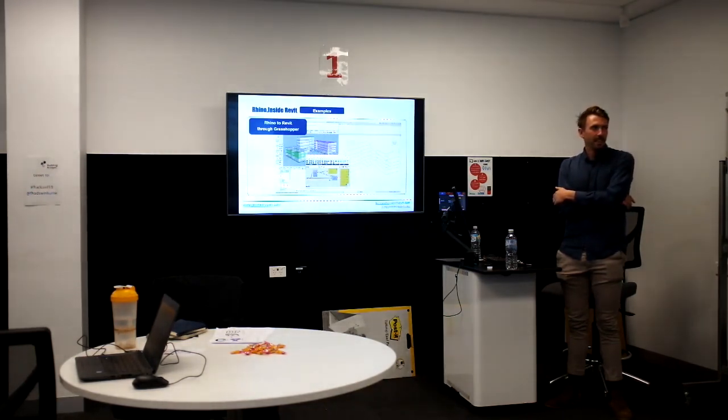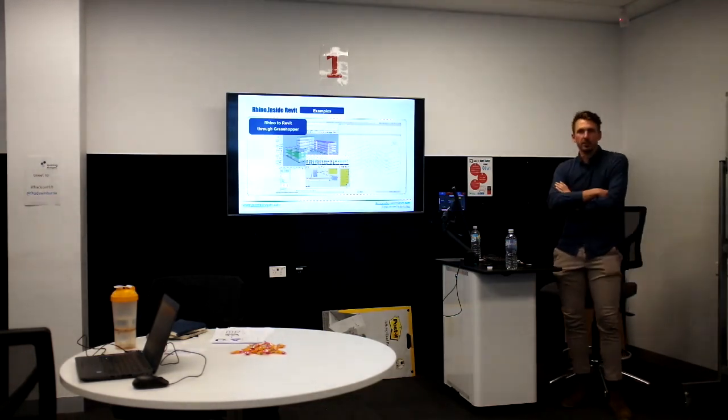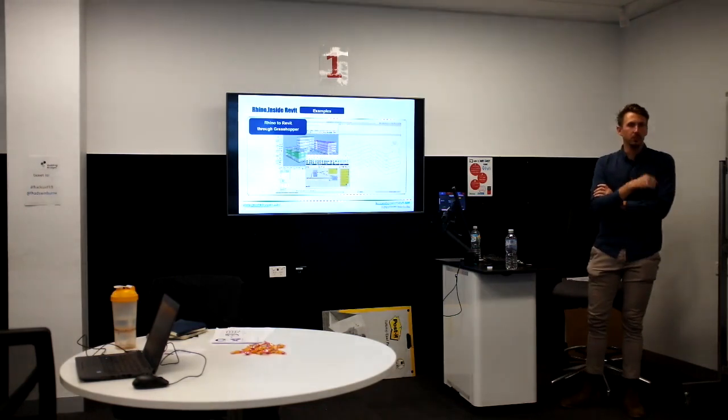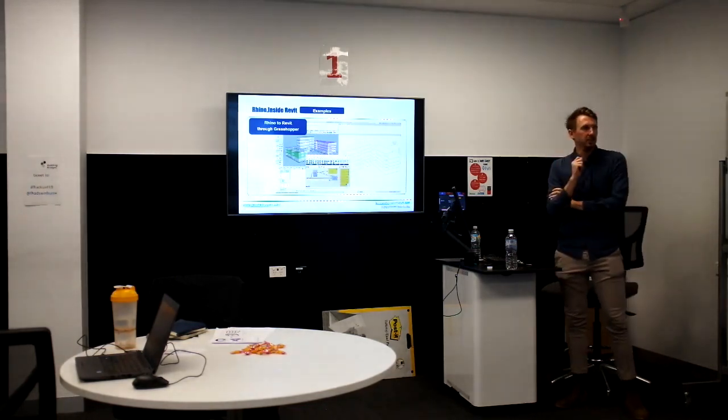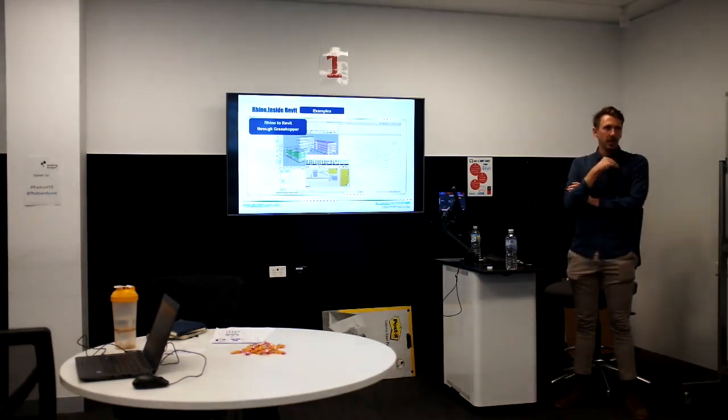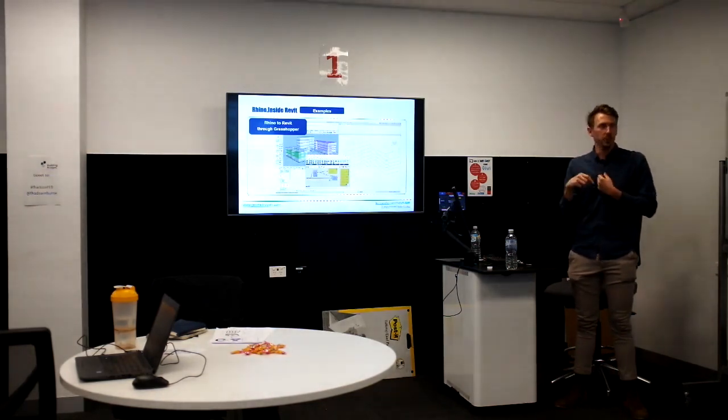And with the custom bake tool that you have, you directly bake IFC elements. It's not baking, you basically just link IFC directly to Revit. No, it's creating Revit elements, but we just use IFC as the transfer mechanism. Basically, we have our own IFC importer.